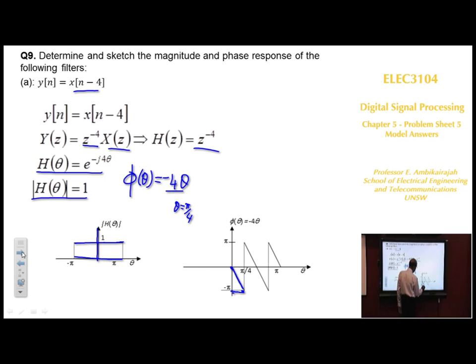Now if it reaches minus pi, it must do a 2 pi jump, and then it's reached plus pi. We have got nothing to do with the 2 pi jump, it's nothing to do with the magnitude response. There are no zeros here. The magnitude never goes to 0 here, it's all flat. Then it goes in parallel, comes there again at some point it's pi, jumps again and then goes down.